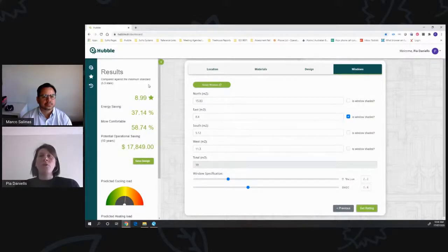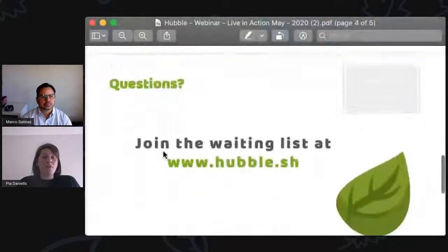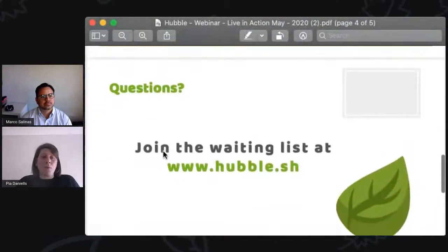In this one, the floor insulation has made a significant change to the building, so we couldn't get away with lower performance glazing rather than using high performance glazing, as was expected previously. But again, it just depends on site location and all those types of things as to what is physically possible. Not all sites can allow for floor insulation, so that's something that would need to be considered as well.